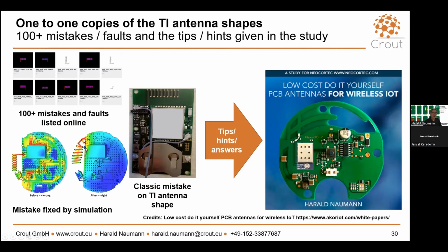There is the shorting point, and the blue bubble here is a capacitor. That means with the capacitor we could switch between 868 megahertz and 915. So it is not possible to build an antenna that is covering the American band and the European band on this small PCB.